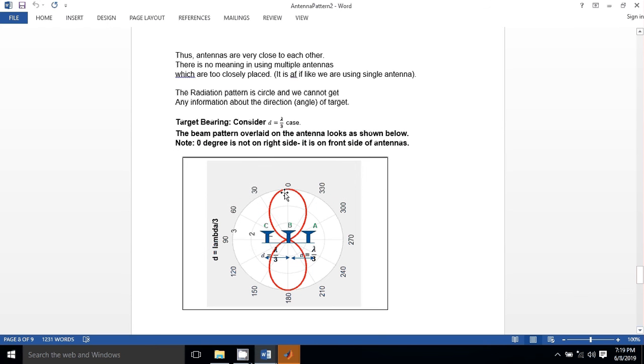When we go for more antennas, the beam directivity will be more. The power radiated in this particular direction will be more, because when we go on increasing the antennas in the horizontal direction, the directivity of the beam increases, or the beam becomes sharper. If we use 4 antennas, 5 element antennas, 6 element antennas, this beam will point more, or the power radiated in this 0 degrees and 180 degrees will be more.